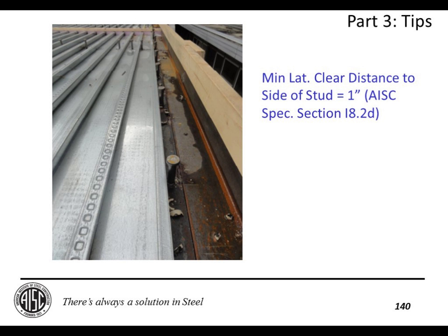Here we have a minimum lateral clear distance to the side of the stud of 1 inch being violated because the deck didn't lap out correctly. So they just shove it over to the deck and shove it over to the stud and try to make it work. So we had to pull the deck off of it a little bit.